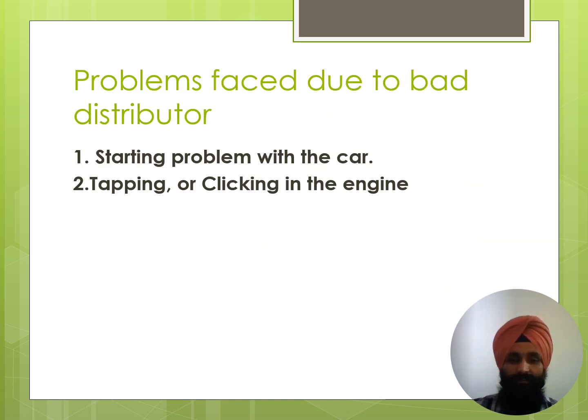Now let's see which problems we generally face due to a bad distributor. The first and most obvious problem is a starting problem with the car. Sometimes we notice that we are rotating the key, trying to start the car, but the car is not getting started.